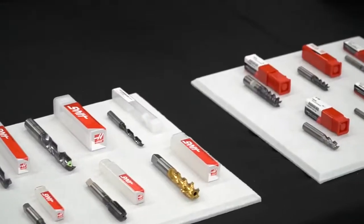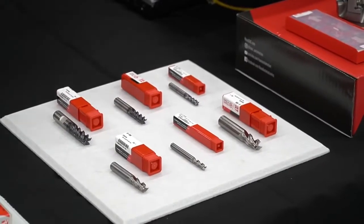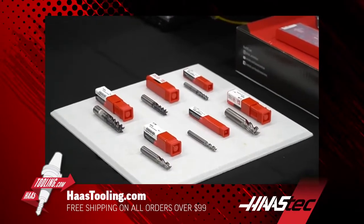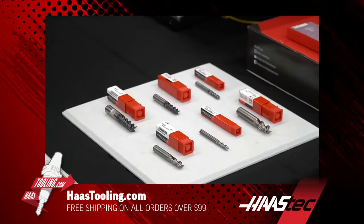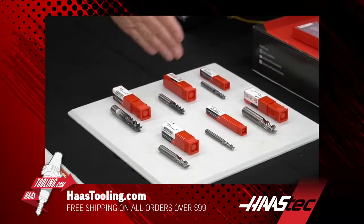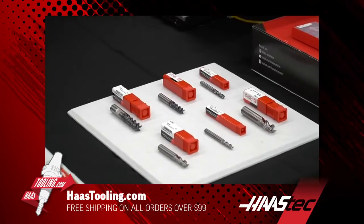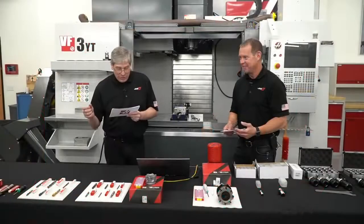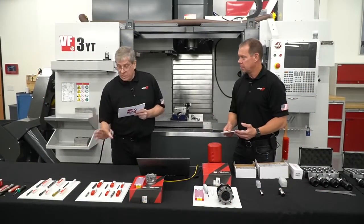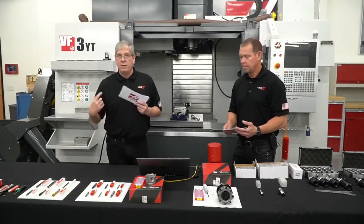End mills, solid. Here's a range of solid carbide end mills that we carry. First, we're going to start with the 3 fluters here. We've got a 1/4 inch, 3/8, and 1/2 inch version of this to show, but we carry these in 10 sizes. Again, primarily designed to rip aluminum. All of our 4 flute and 5 flute end mills are talon coated, titanium aluminum nitride. We carry those in 15 different sizes for the 4 fluters and 13 different sizes in the 5 fluters. There's also different cut lengths. So again, browse the website, see what we've got.